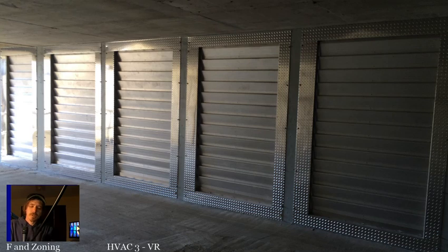There's a couple reasons chillers are usually used in big buildings. Those couple of reasons are efficiency, and it's less expensive to install all that piping than it is to install all the big ductwork you need. It is a more economical system overall. So that's why you see chillers. Remember the flash economizer we talked about? Flash economizers are often used on screw compressor chillers.